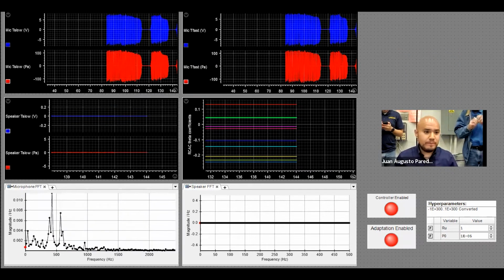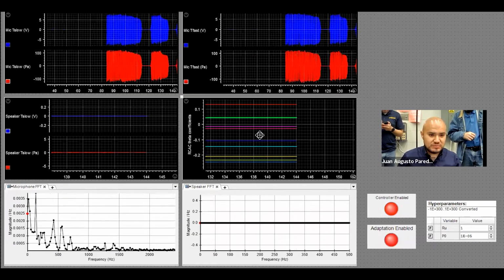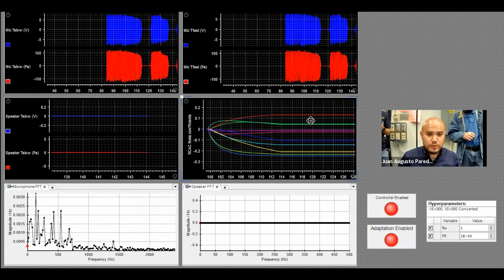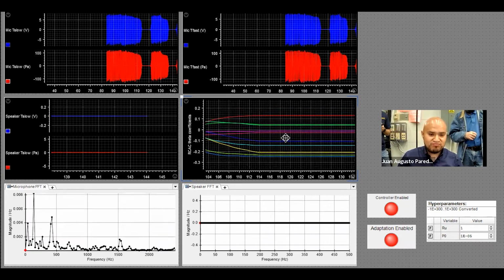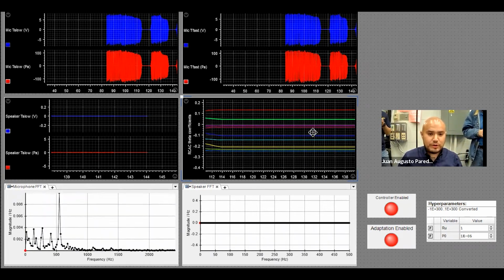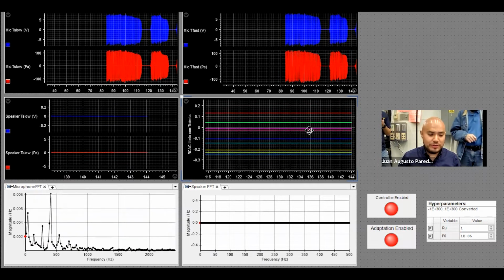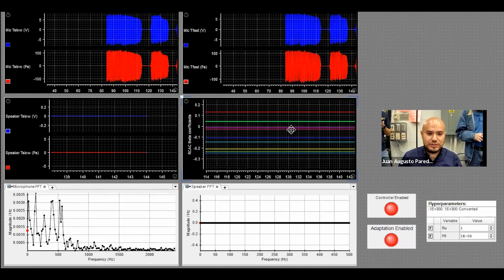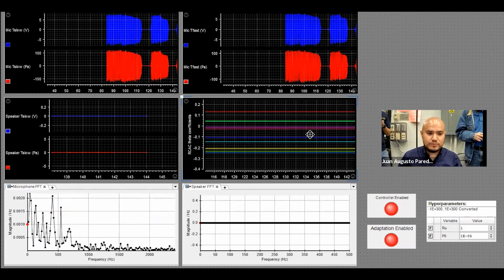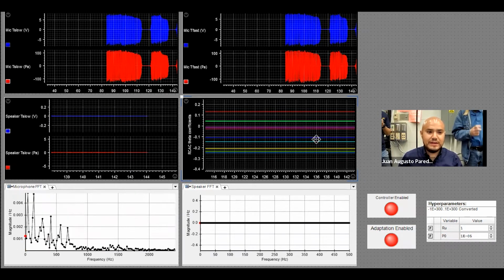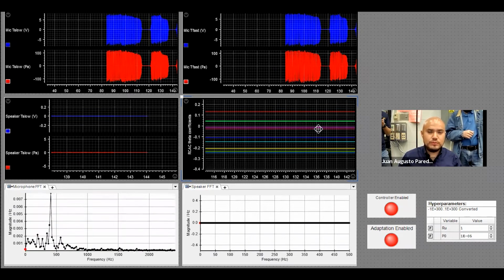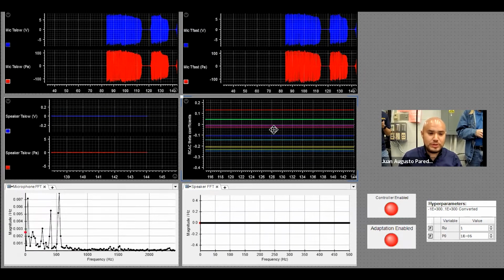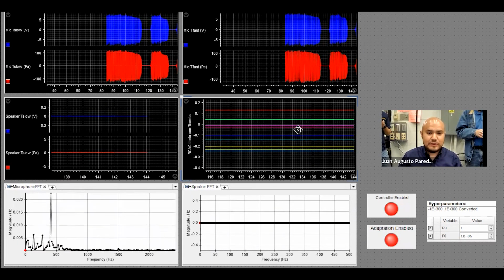So as I mentioned before, once we reached the stabilization of the oscillations, we disabled the adaptation and we kept the controller coefficients static. Then we disabled the controller, and immediately after, the oscillations came back. However, once we enabled the controller, the digital controller with the static coefficients was able to control the oscillations, meaning that RCAC reached a set of coefficients that could be used for later tests without any need of further adaptation.